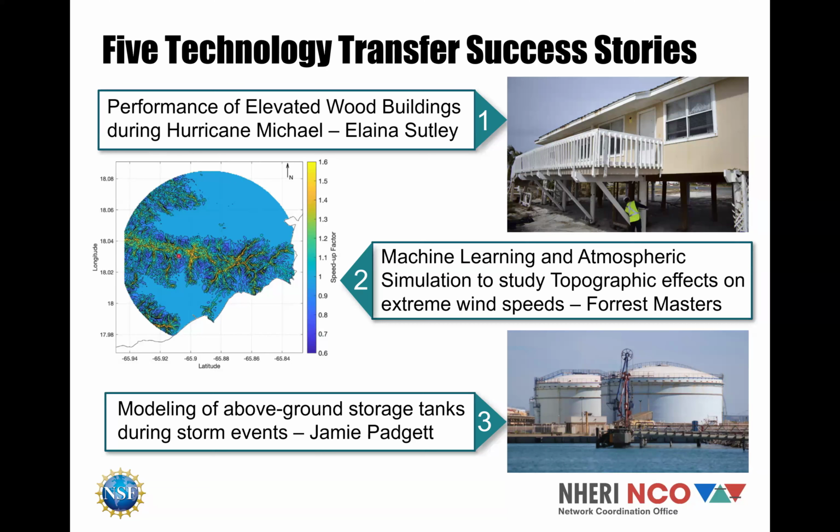So now maps are available on ASCE 7-22. You go into the hazard tool, and we have wind speed maps for Puerto Rico, for Virgin Islands. Guam also, I believe, has been done, and Saipan. So eventually all of the territories will have these topographic maps, and I thank Arthur Chiu for initiating a lot of that work.